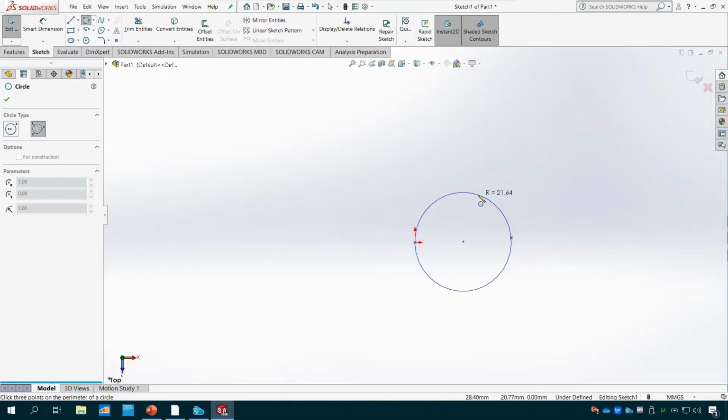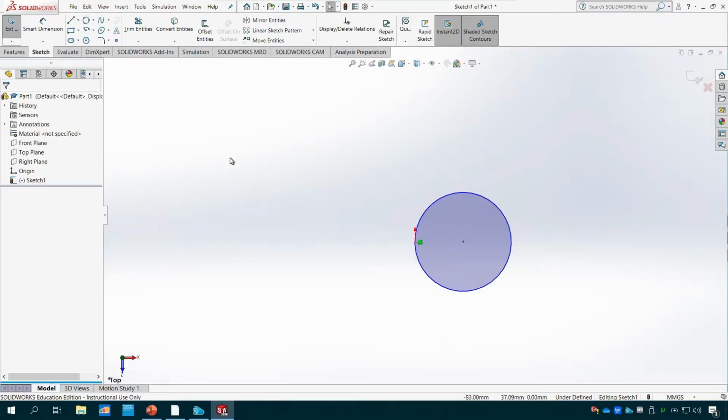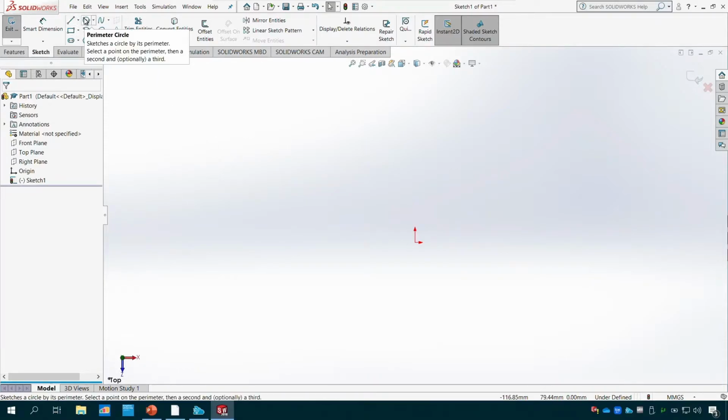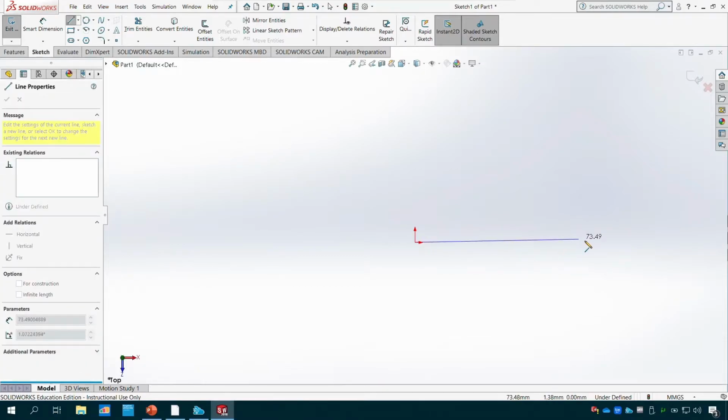And if you're happy with everything, you just click once on it and you can see now I just created a circle there. So let me do a Control Z. We already created a line, we went through the rectangle, we made the centers, and now let's talk about, for instance, making an arc. Let's say I have that line and I want to make an arc. Let me make, yeah, I think that's good.